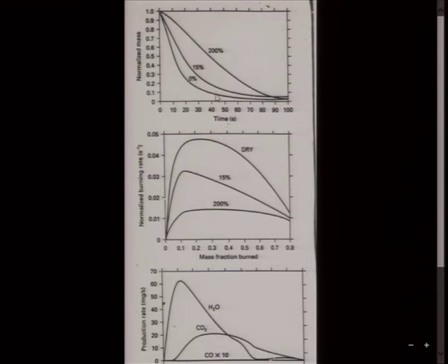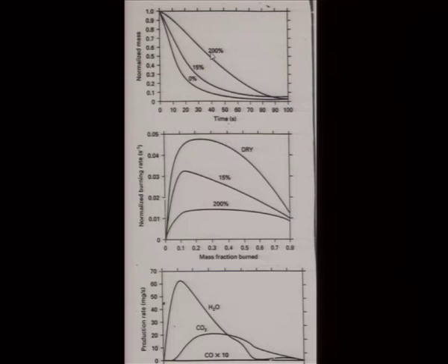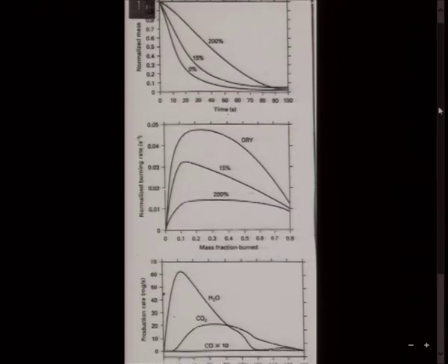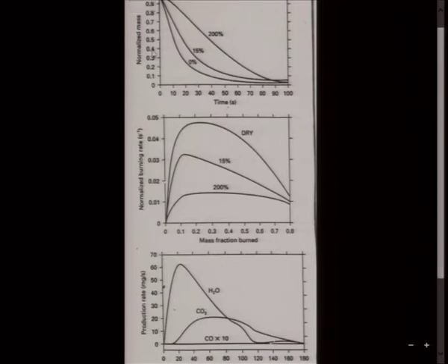If it is dry, then it's more like pyrolysis happening. But in other cases, there is also drying taking place. And if there is more moisture, then the rate of mass loss is less. If there is less moisture, then it's more pyrolysis. So the drop that you see, the slope that you see, is actually higher. And that's normalized mass, m by mi.